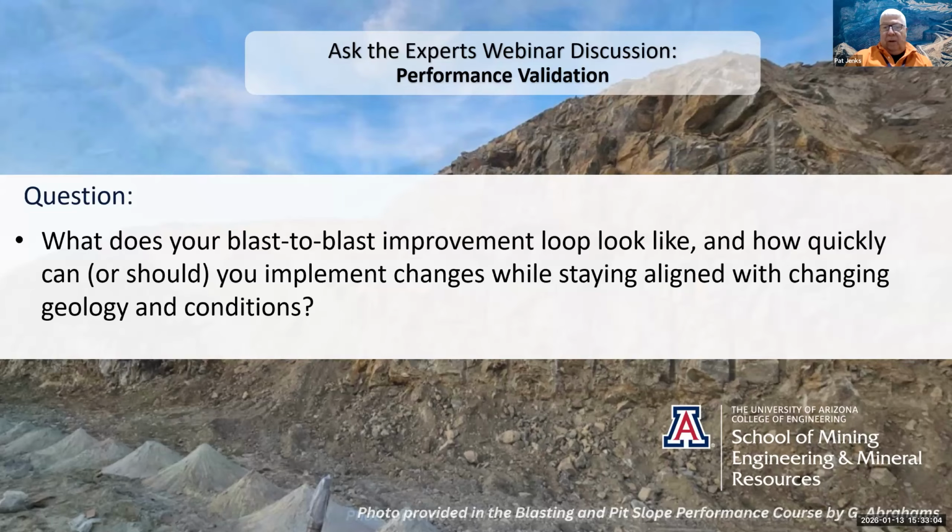So the videos are a great tool to enlighten you and get you thinking about how to improve on that next bench. And then look at the slope performance data from our monitoring tools, such as radar or prisms. Do we have evidence of blast-induced deformation in the radar or prisms? Let's start thinking about what we can do there.